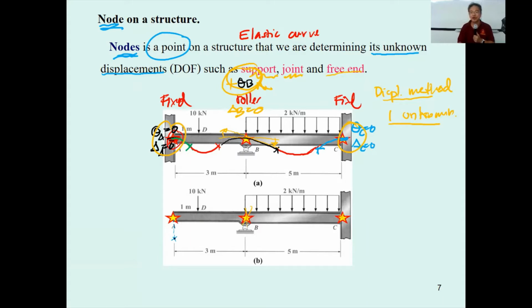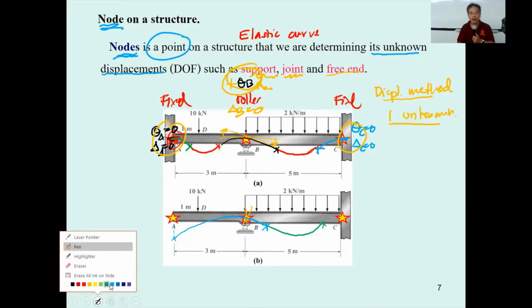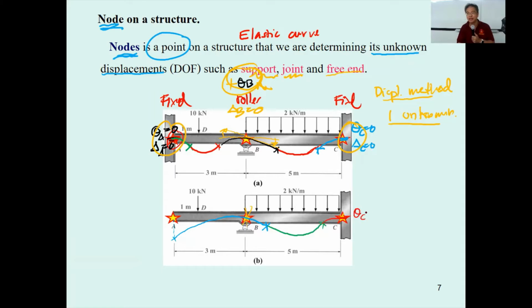And then for sure, the beam is going to have some kind of deformation. It's going to have the inflection point here, and then it's going to be concave upward. Then it's going to go concave downward and link to this point, since theta sub C is 0, since delta sub C is 0. And over here, theta sub B is still the unknown. Delta sub B is 0.